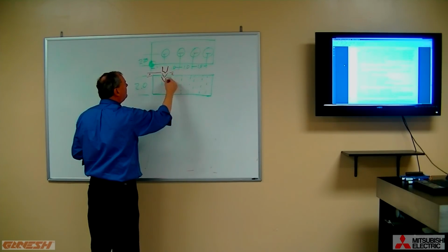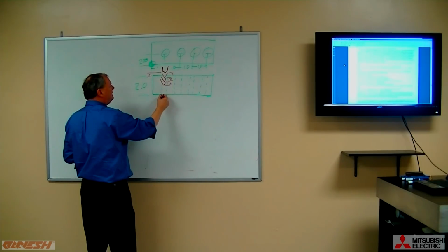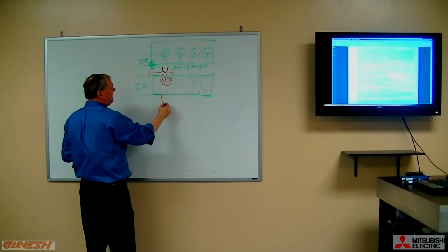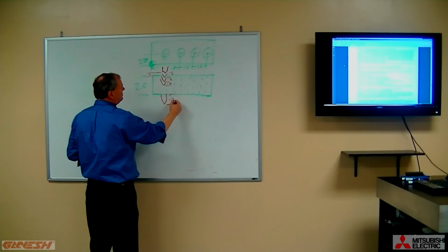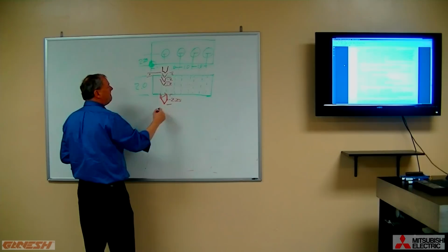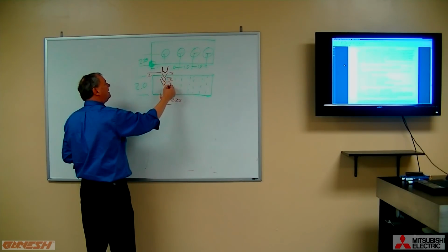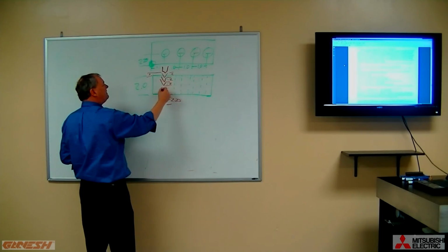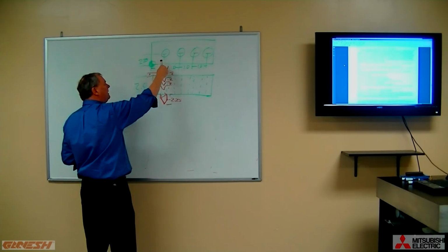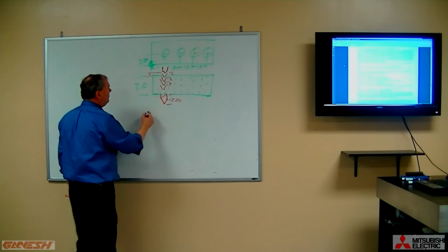So another 0.2, and another 0.2, and so on until it reaches a final depth that should probably be something like minus 2.25 to clear the tip of the drill past the material. So you would have to do a lot of calculation. You would have to divide all this up by 0.2. But the G83 drilling cycle would be really easy.